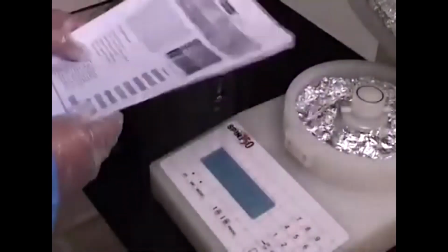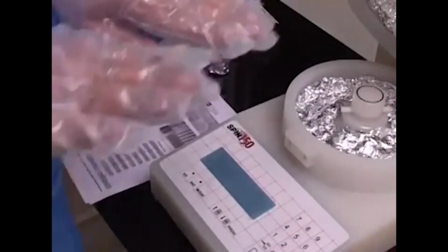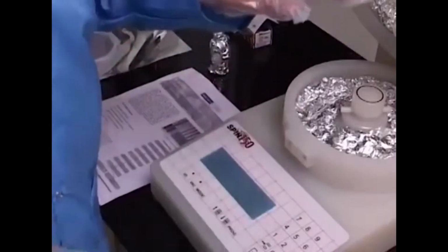And it also mentions that you have to hold at a certain spin speed for close to 90 seconds for the spin coating to be uniform. I would also like to illustrate here that the resist, being a thick material, needs a little bit of time for uniform coverage over the whole surface.